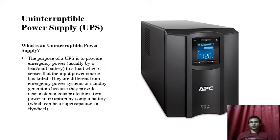Uninterrupted Power Supply, UPS. What is an uninterrupted power supply? The purpose of a UPS is to provide emergency power, usually by a lead acid battery, to a load when it senses that the input power source has failed. They are different from emergency power systems or standby generators because they provide near instantaneous protection from power interruption by using a battery, which can be a supercapacitor or flywheel.